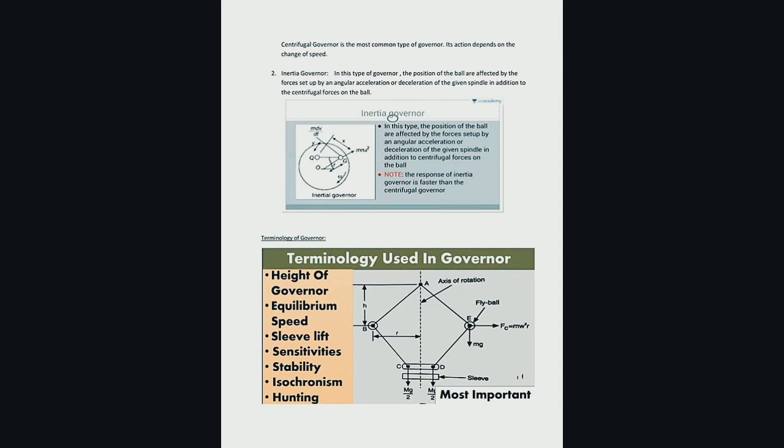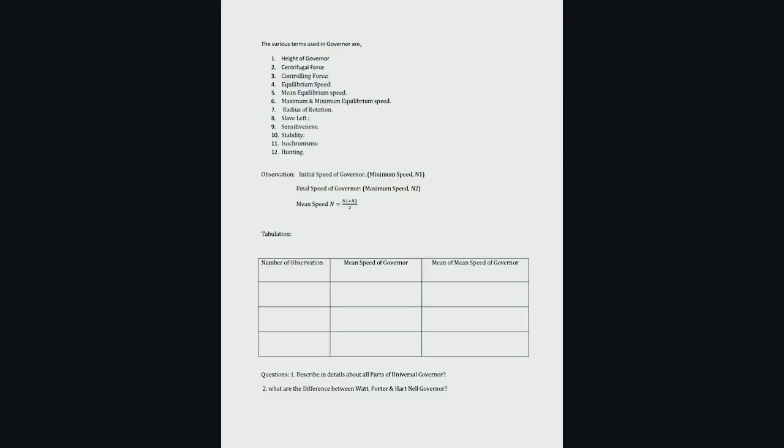Base: this is the strongest part of the machine, with the ability to absorb the vibration produced during machining. Cast iron is a suitable material to absorb the various vibrations induced during various types of operation. Ram: the ram carries the single point cutting tool and reciprocates on the column guideways. Work table: this is generally used to hold the machine vise where the workpiece will be held properly for various types of operation. Column: it is a box-like structure which is mounted on the base, with a driving mechanism inside the column. Clapper box: the clapper box holds the tool firmly during its cutting stroke and idle stroke.